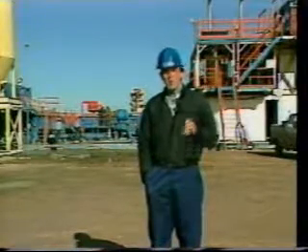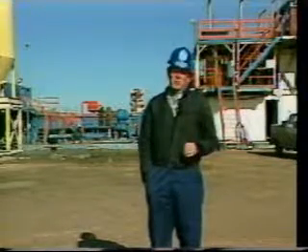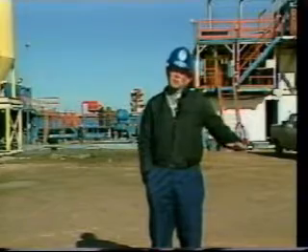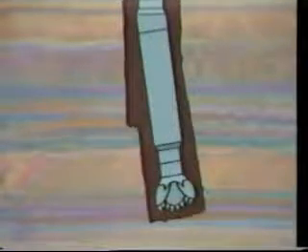Directional drilling involves kicking the well off or deviating it from a straight down path and then maintaining that direction to the final target, adjusting course along the way. One method of deviating a well uses a bent sub to position the bit to point in the direction required. Downhole motors use a turbine powered by the circulating drilling mud to turn the bit. Jet bits are also used to wash away one side of the hole with high-velocity drilling mud and create a new avenue for the bit to follow.